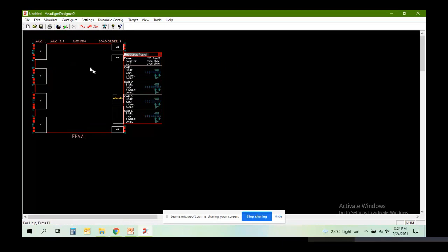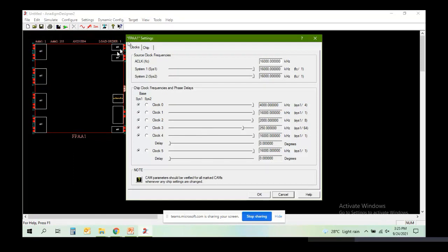And you can check the power consumption also. You see, this particular function is taking 39 plus or minus 2 milliwatt. So power resources you can check. And one more important function is, there are no analog functions available inside the FPAA now. I'll just double click inside the FPAA. You will get a window like this.